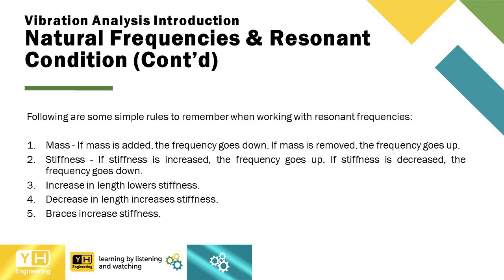Following are some simple rules to remember when working with resonant frequencies. 1. Mass. If mass is added, the frequency goes down. If mass is removed, the frequency goes up. 2. Stiffness. If stiffness is increased, the frequency goes up. If stiffness is decreased, the frequency goes down.